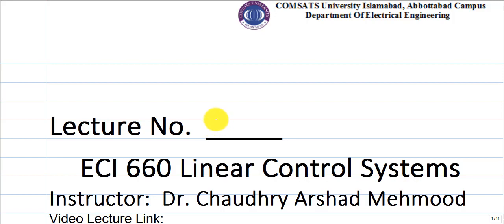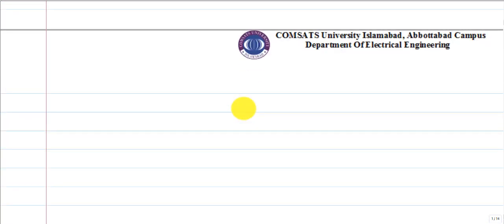So today's lecture of linear control system is 15. In this lecture video, we will be discussing the canonical forms. In the previous two videos, we have seen the controllable canonical form and the observable canonical form, and we have seen how, with a small manipulation of the transfer function, we can obtain the different forms of the state space model. Today we will be looking at another canonical form, which is known as the diagonal canonical form.